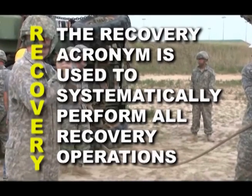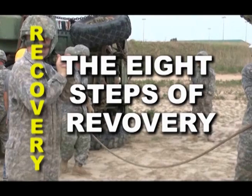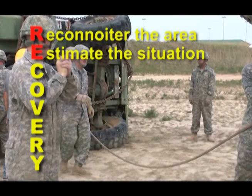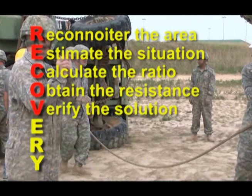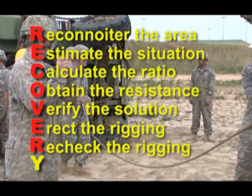The recovery acronym is used to systematically perform all recovery operations. Before you begin to recover a vehicle, you must understand the 8 steps of recovery. Reconnoiter the area, estimate the situation, calculate the ratio, obtain the resistance, verify the solution, erect the rigging, recheck the rigging, and you are ready to safely recover the vehicle.